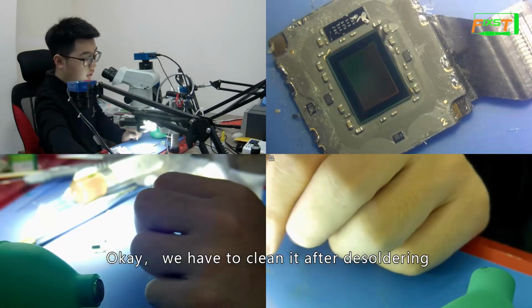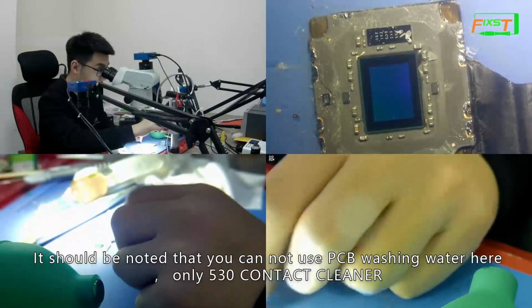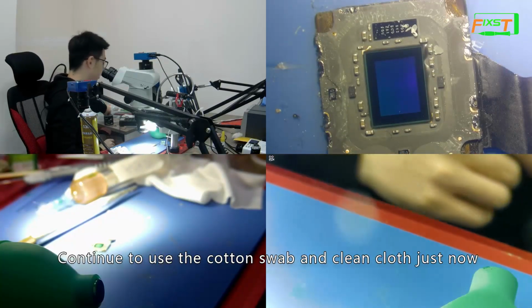Okay, we have to clean it after desoldering. It should be noted that you cannot use PCB washing water here, only 530 contact cleaner. Continue to use the cotton swab and clean cloth from just now.